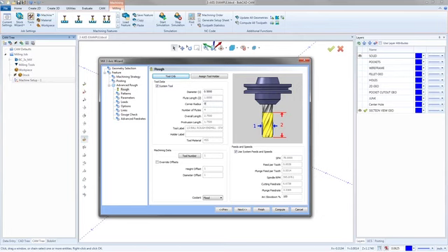If you went in and set up a tool crib beforehand, that's definitely the smarter way of doing these things, just because you have more control over exactly what tools get picked. And BobCAD doesn't pick a random tool. It'll always try and pick a tool from the category that you picked it from. So it's not going to default to a 1/2-inch flat end mill if I don't have a 1/2-inch flat end mill in my library. If I had a 3/8 flat, it would actually give me the 3/8 over this 1/2-inch, just because it's one that I have in my crib over my library.